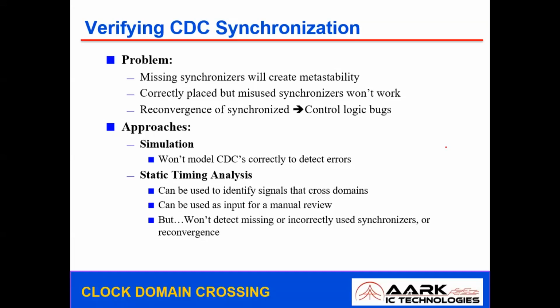Now, what is the alternative? The alternative is gate level simulations. Gate level simulation is used to identify the X behaviors, that is unknown, where it might be either 1 or 0. The basic importance of gate level simulation is to identify these asynchronous behaviors. So how do we get asynchronous behaviors? It might be a change in the phase of clocks, or different clocks operating in a single block, or a scenario of two blocks operating with two different clocks and a data transfer between them, which again leads to multi clock domain crossing. These issues can be addressed only at the gate level simulation stage. You cannot figure out these effects either at the zero delay simulation stage or at the static timing analysis stage.